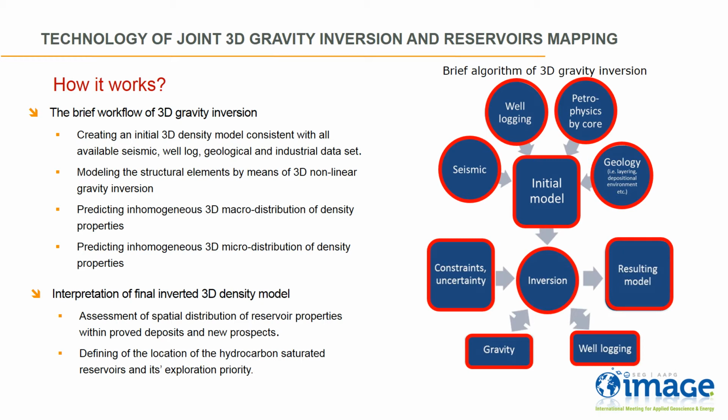All available data should be integrated into one coordinated 3D geological model. Rock density is used as the parameter for this model because rock density is directly related to gravity and, on the other hand, is a good indicator of rock lithology and fluid saturation of rock.